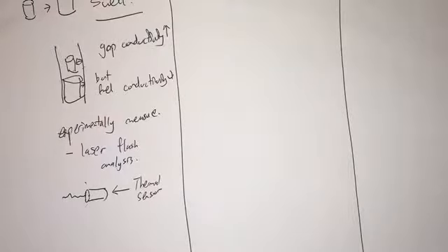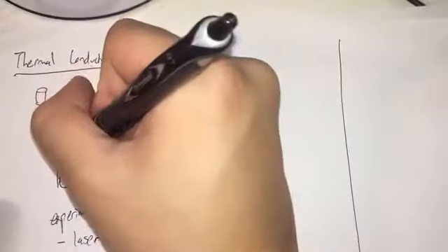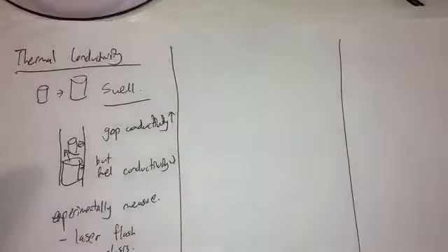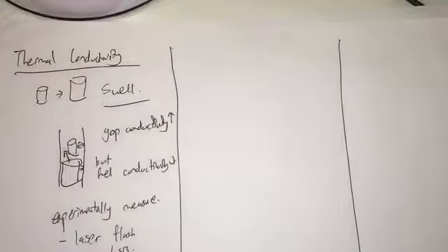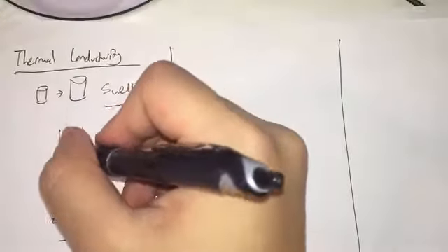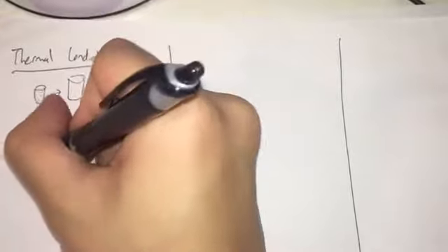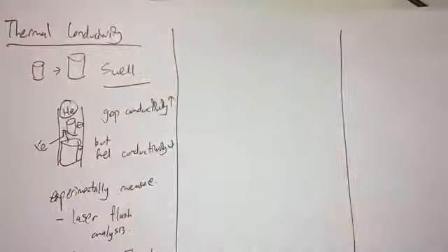How about gas release out of the fuel? As the fuel swells, the fuel cladding gap decreases, and the thermal conductivity between the fuel and the cladding increases. But when the xenon is released from the fuel into this gap, which is also called the plenum, it's released into an environment that's normally filled with helium.